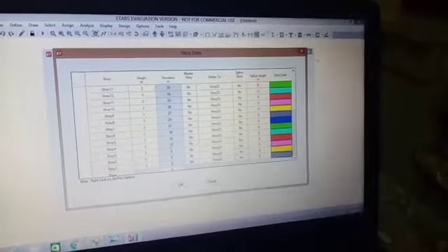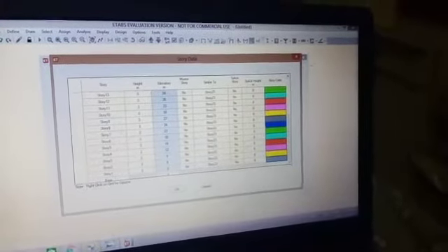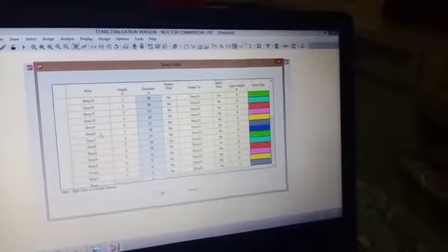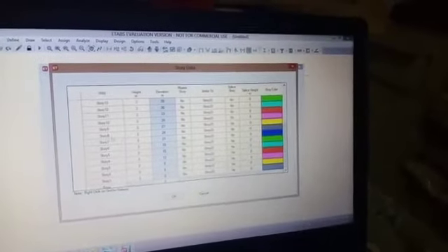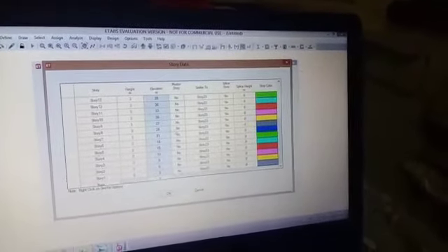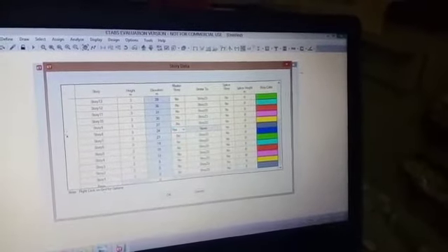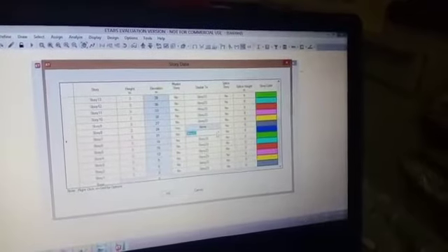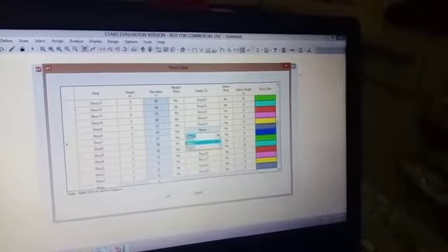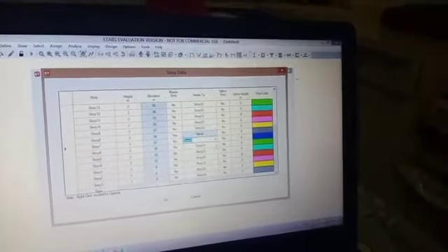Now go to any one story between story 1 to 8 since all of them have to be similar. Choose story number 8 and now make it the master story and change all the other stories as similar to story number 8.